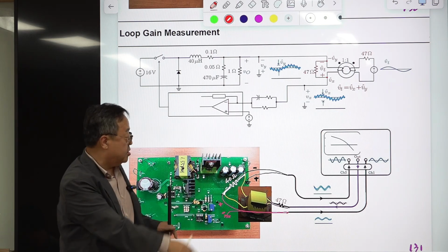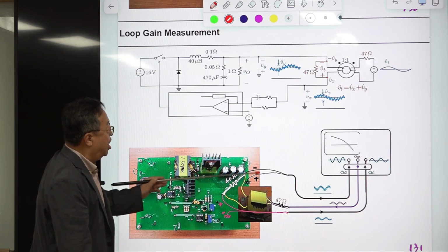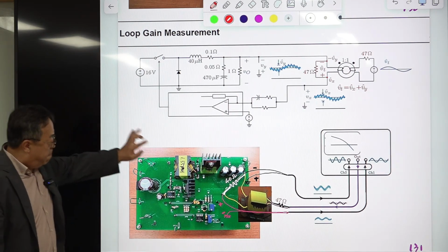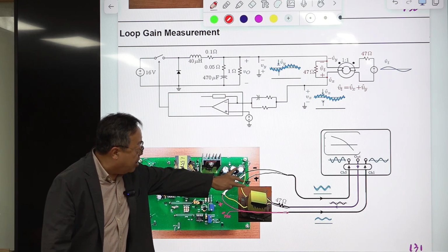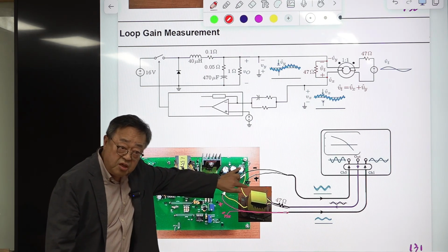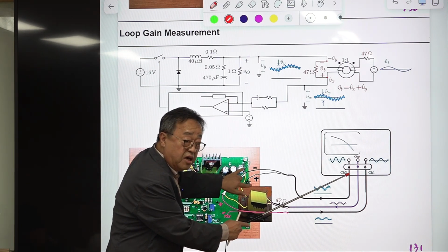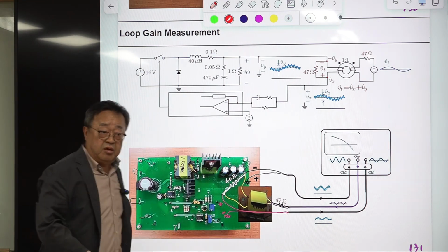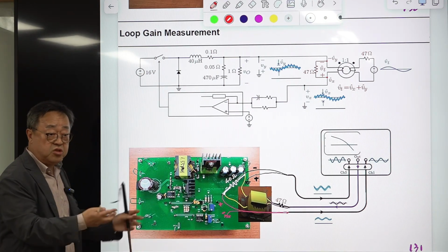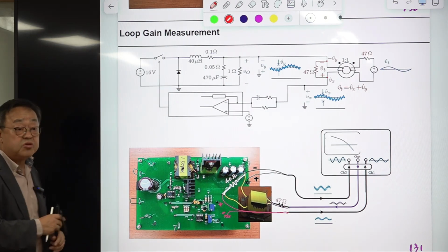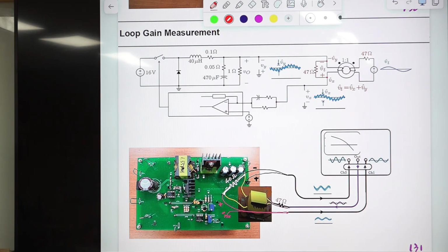But using a high performance differential probe is okay. This is very good. For high voltage output applications, this can be very high voltage, 400 volts. If you connect directly, then this guy will be dead. This part will get fired. To avoid that, you need to use an attenuated probe, something like that. The performance is worse than the regular one. If you add something, it becomes worse and worse. That is the law of nature.